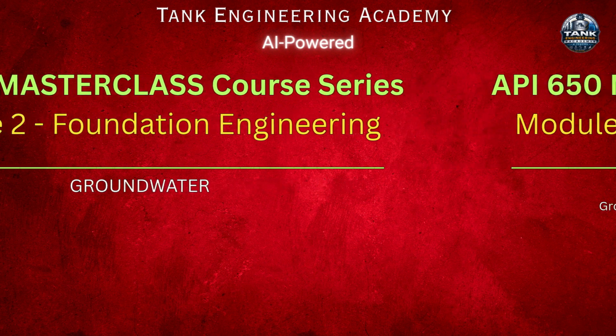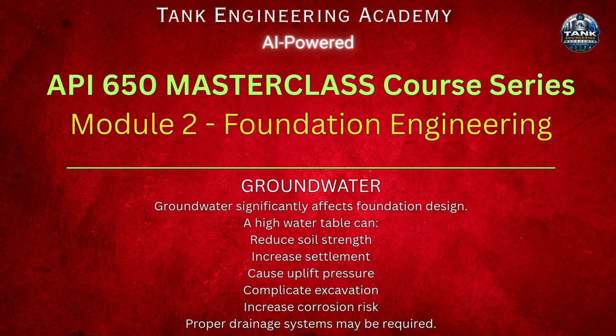Groundwater. Groundwater significantly affects foundation design. A high water table can reduce soil strength, increase settlement, cause uplift pressure, complicate excavation, and increase corrosion risk. Proper drainage systems may be required.